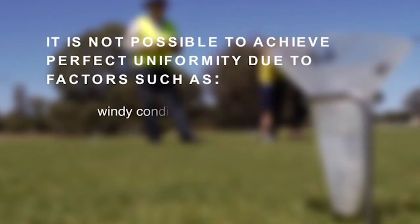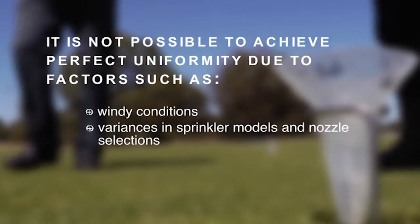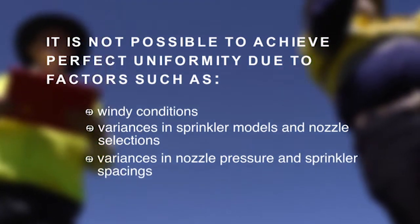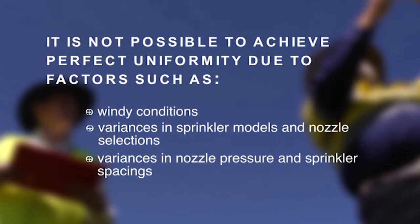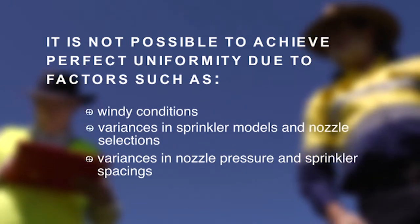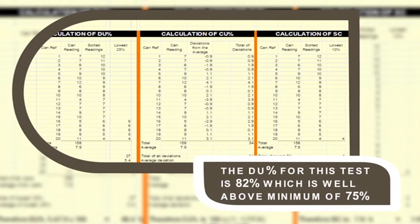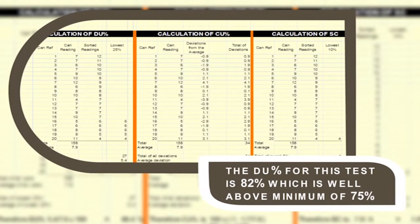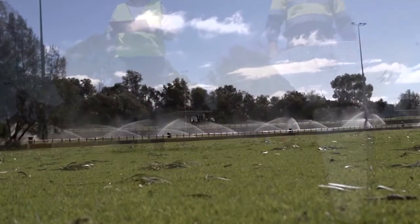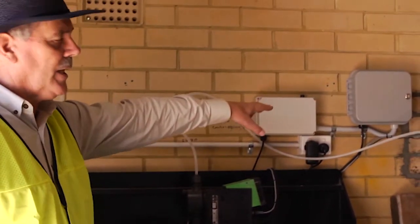However, it is not possible to achieve perfect uniformity due to a number of factors which may include windy conditions, variances in sprinkler models or nozzle selection, and variances in nozzle pressures and sprinkler spacings can all contribute to lowering uniformity. In the case of this test, the DU percentage is 82%, which is well above the industry accepted minimum of 75%. We hope that this has provided an insight to the process of assessing a sprinkler irrigation system.